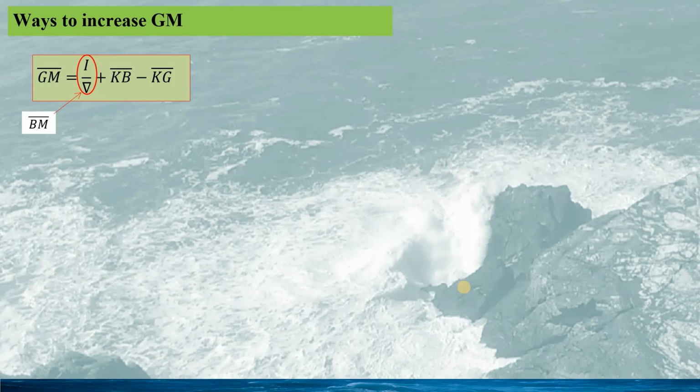In this slide, we'll show how to increase the stability of the floating structure. This means we need to increase the inertial metacentric height, Gm. Based on the detailed formulation of the inertial metacentric height, Gm, given by this formula, we can have different ways to increase Gm.